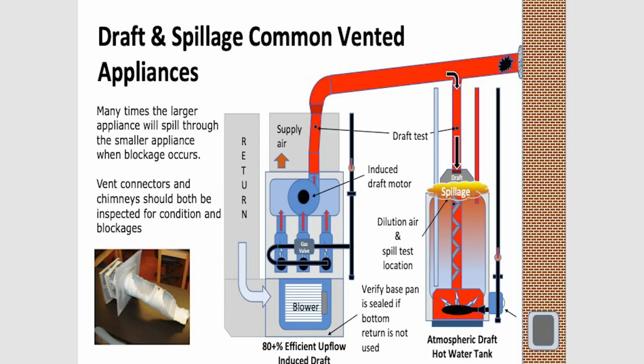Chimney liners, right? Chimney liners collapse. I think I got a slide, but it's not on this one. Chimney liners collapse, chimney liners fail, chimney liners aren't put in correctly, guys don't pay attention. Whenever you see a common vented appliance, you need to make sure that when this appliance is running, you don't have a problem. There's a chimney liner right there in the bottom corner of it. So that is a very common problem.